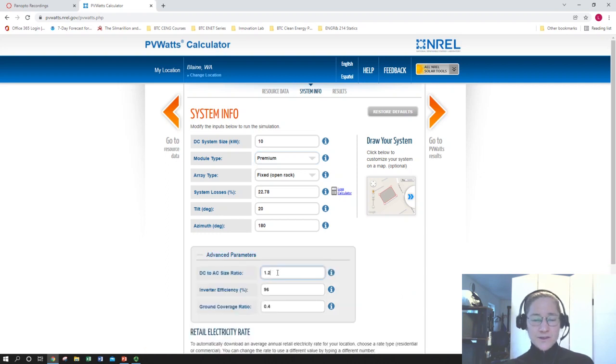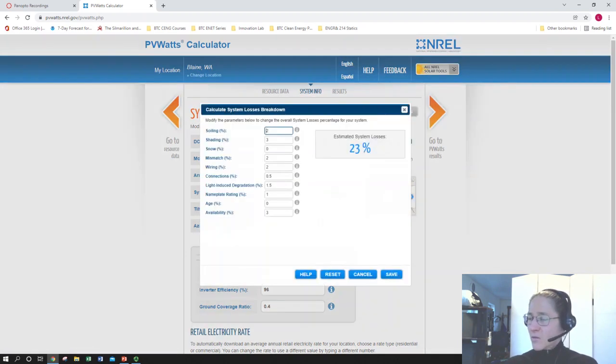They're going to assume they are going to configure their inverter, if they have to use one, for a more ideal size ratio. And let's look at what we can assume for system losses for these folks, because they're in a little bit different situation. So these folks are still going to have 3% soiling losses. Example 1 data input.